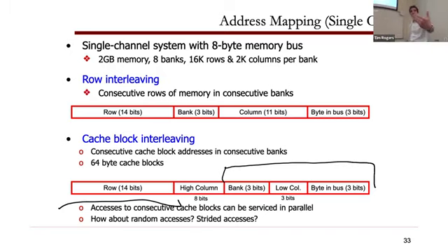So lighting them all up, if they all take the same amount of time, if you RAS, and then it all comes back at kind of the same time, and then you feed it out through the muxes, that'd be better than just opening the row and reading 8 times. You still have to read 8 times either way, right? So it may not be an advantage to do it that way.